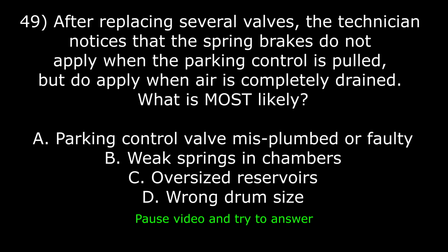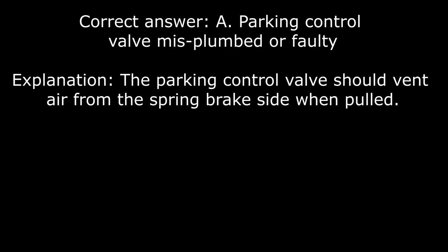49. After replacing several valves, the technician notices that the spring brakes do not apply when the parking control is pulled, but do apply when air is completely drained. What is most likely? A. Parking control valve misplumbed or faulty. B. Weak springs in chambers. C. Oversized reservoirs. D. Wrong drum size. Correct answer is A. Parking control valve misplumbed or faulty. Explanation: the parking control valve should vent air from the spring brake side when pulled.